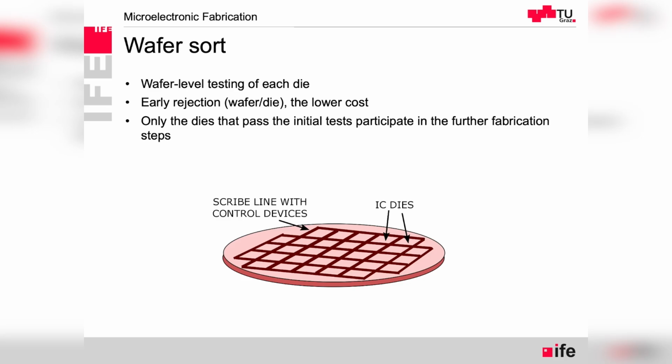So first thing is, still before dicing the wafer, we have the possibility to test that the individual dies that will be later separated are working properly. So we're going to test the circuits by putting needle probes one by one, as well as in these red frames.